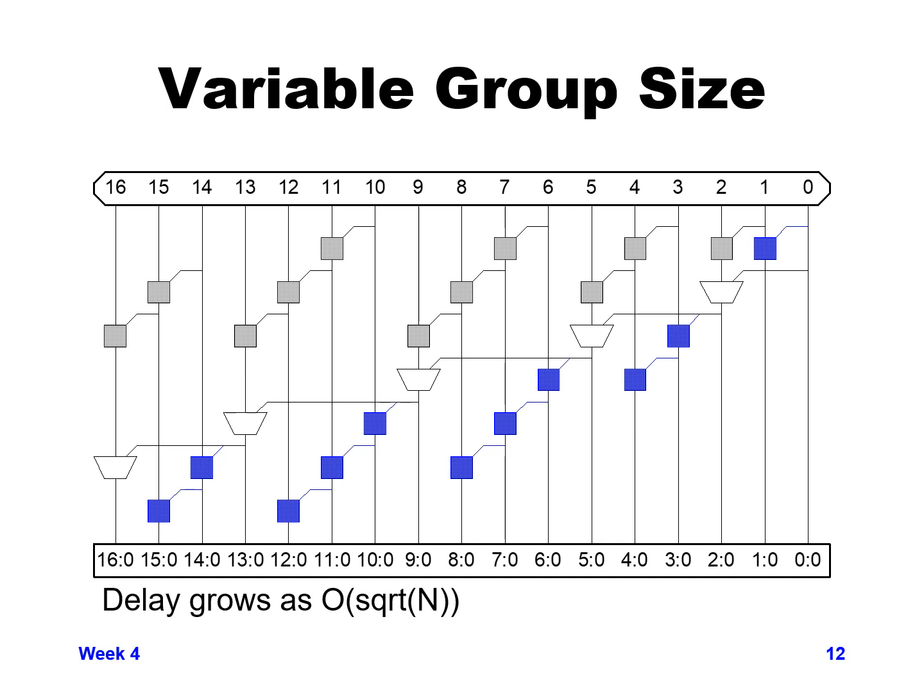Now we go through that skip stage and we start going through our skip stages till we get to the second to the last skip stage. You can see we go through one at bit 2, second one at bit 5, third one at bit 9, and a fourth one at bit 13. And then at this point, our longest delay is through the final 2 blue carry stages at bits 14 and 15, and then we get to the end.